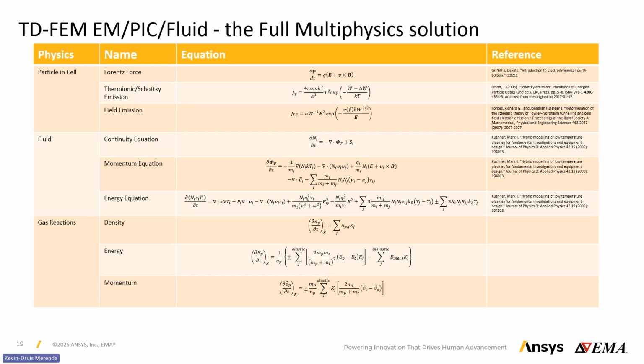The PIC solver is a tool that allows us to track a statistically significant number of particles in the mesh. You can imagine that there's no way we can track 1e20 electrons per meter cubed in some of those models. Computationally, it's typically done by making sure that you have enough particles at each mesh element to properly sample the energy of the plasma in that mesh element.